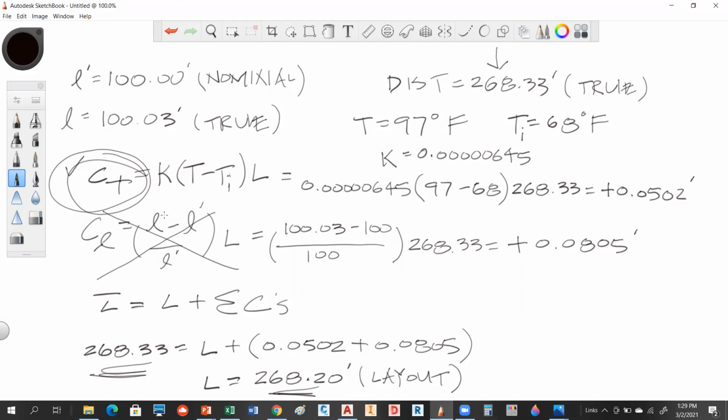So it's kind of the same thing with light. As that temperature and pressure change, that's going to change your air column. It does produce what's called a parts per million correction, what we call a ppm correction. And it's small, parts per million, but it does make a little bit of a difference when you shoot distances on EDM, but you don't have to worry about this specifically. Okay, so there is a ppm correction. I think you mentioned, did I hear somebody say something about the prism?